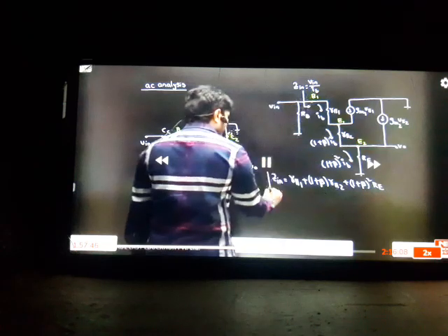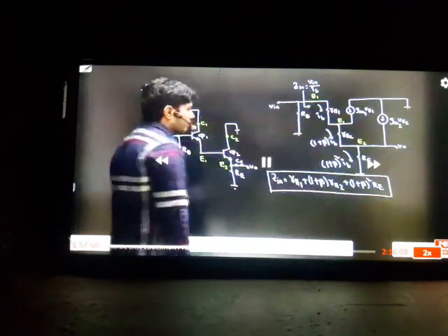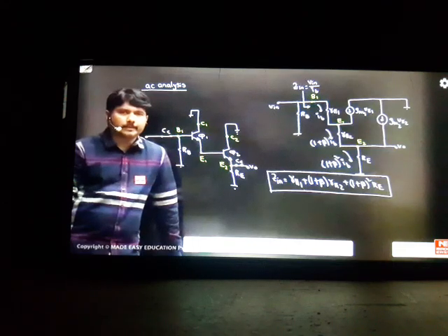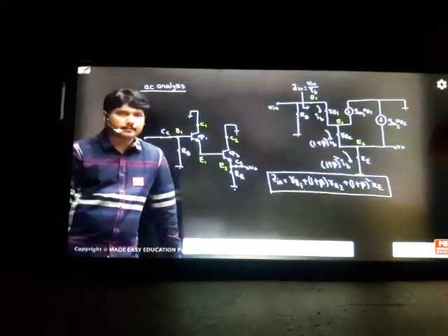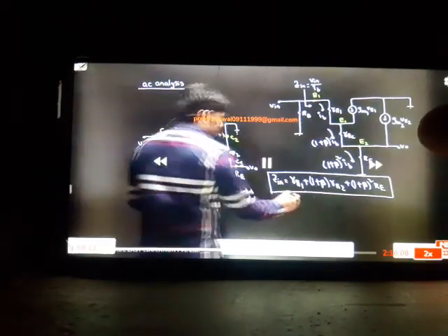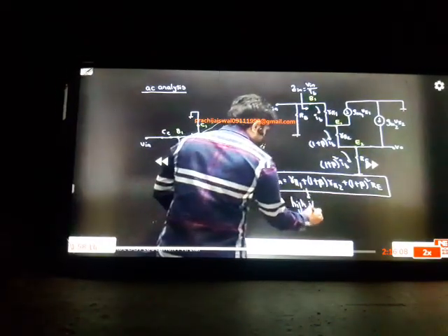So what is special about this topic is, you can see the highest input impedance in our amplifier circuits. This is the highest input impedance. That's why the main purpose of a Darlington pair is, wherever you have a loading effect, it can easily be solved by this circuit, because this is my input impedance. It's an accurate, exact input impedance I calculated. So this is a high input impedance device.